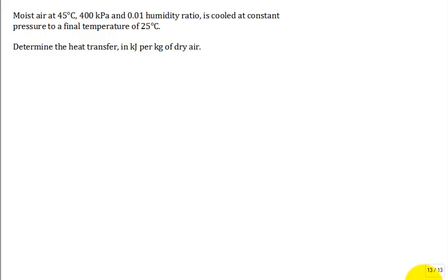So I thought I'll make up a problem that'll illustrate this phenomenon. So here's the problem. I start with moist air that's fairly warm, 45 degrees C. It's at high pressure. It's just been shoved into the tank. And it has the humidity ratio, which is the ratio of how much water vapor there is per kilogram of dry air. That was in a lot of outdoor air that gets ingested into these devices, 0.01 humidity ratio. I was going to say percent, but it's just 0.01. That's a humidity ratio of a lot of outdoor air.